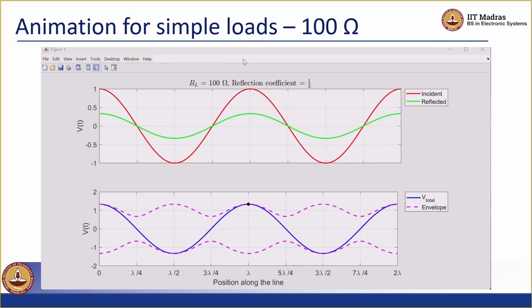All right. With this, I think we can wrap up with understanding of constructive and destructive interferences of sinusoidally fluctuating voltages along the transmission line. We looked at impedance transformations. We looked at the periodicity. We introduced a concept called voltage standing wave ratio. And we looked at how one can actually go through using the rigorous mathematics for a single frequency analysis of a transmission line using the distributed model to describe the voltages and currents at any point along the transmission line.